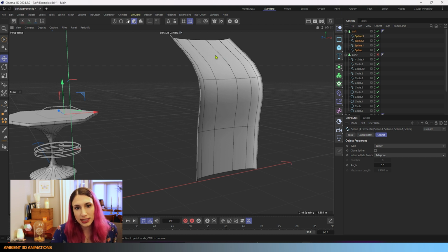So Cinema 4D will have a little bit more trouble figuring out what side should be the outside of the mesh and what side should be the inside. And it uses that direction to calculate what is the normal direction of the mesh. And that's a way of basically saying what's the inside and what's the outside for render calculations, 3D modeling calculations, and so on. So in order to have those calculations go smoothly, you want Cinema 4D to know which direction is your normal direction.